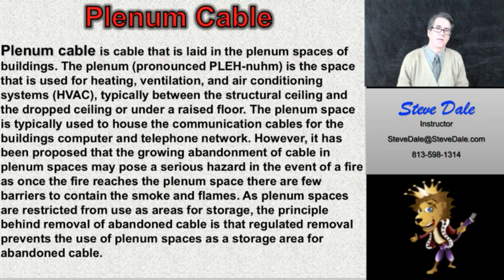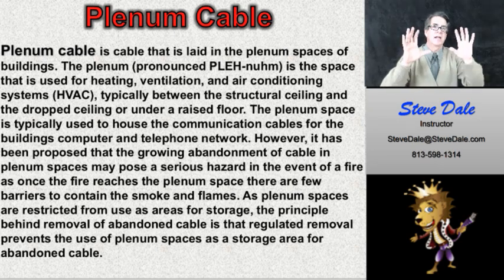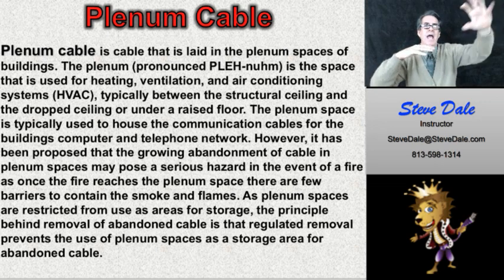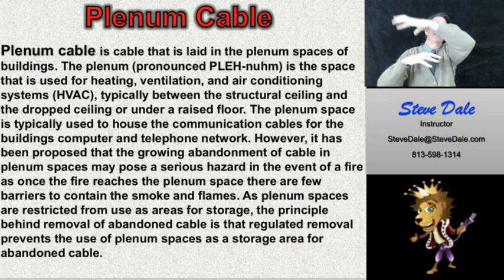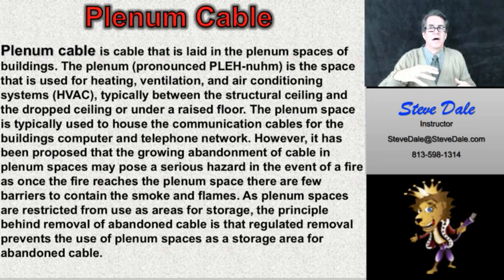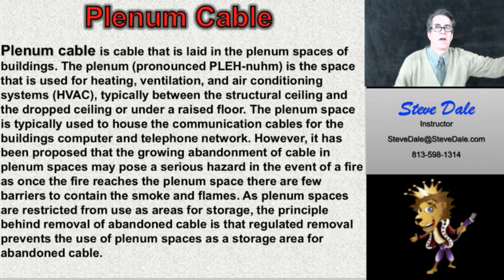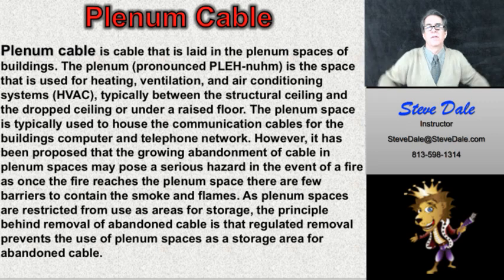Now, not all drop ceilings are plenum, okay? Most of them aren't, but some of them are, meaning that some of them are used for the return. Not a return that has a duct in it. That's not the issue. It's when it doesn't have a duct in it and it just has a grate, and then you have a grate, like say at the very far wall, and you're using the whole area above the drop ceiling as the plenum space, and you're sucking the air from there through the grate that's in the drop ceiling.